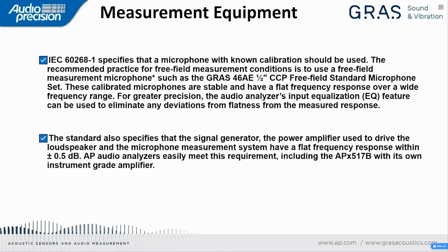The standard also specifies that the signal generator, power amplifier used to drive the loudspeaker, and the microphone system have a flat frequency response within plus or minus 0.5 of a dB. All of our analyzers easily meet this requirement, including the 517 with its own instrument grade amplifier.